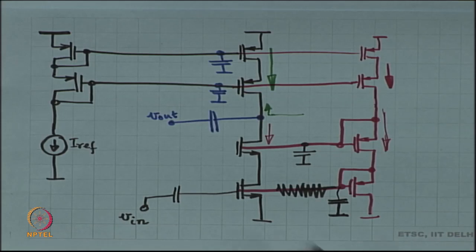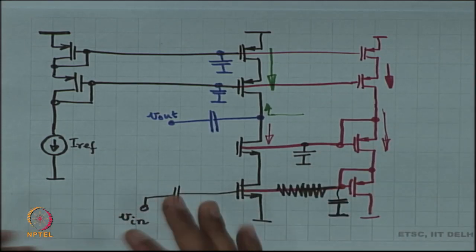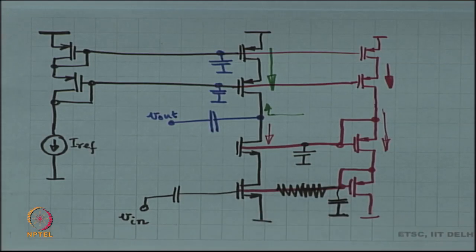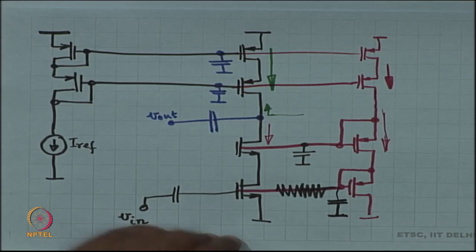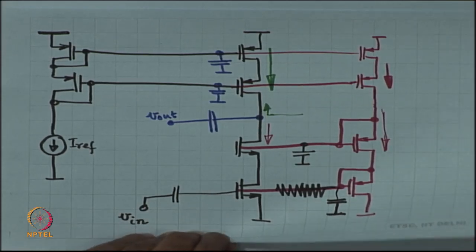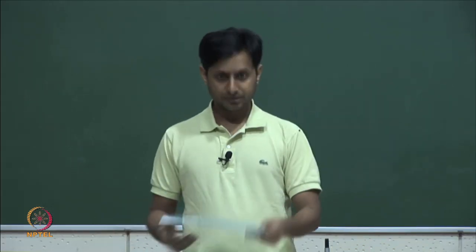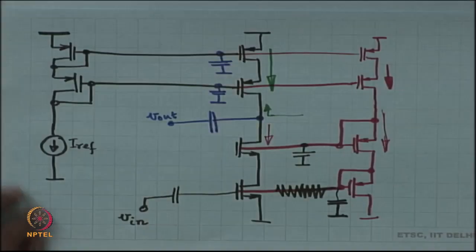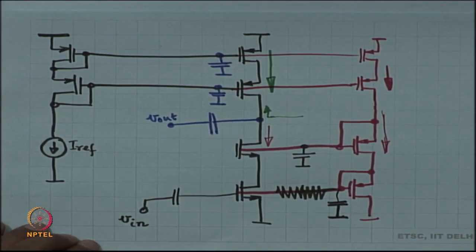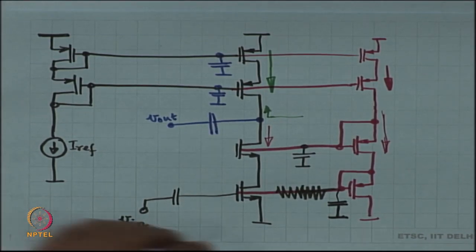Now, that is something very neat when you can control parameters inside the circuit using some element outside, right. I tweak the value of the R, I immediately know that the short circuit transconductance of the circuit is going to be so much. That is something very neat. Okay. So, this is as far as biasing techniques go. There is also an insight as to how you can use current biasing to make your cascode amplifier.